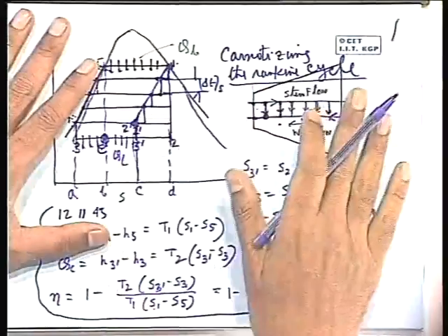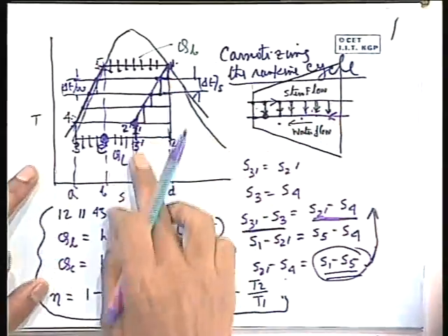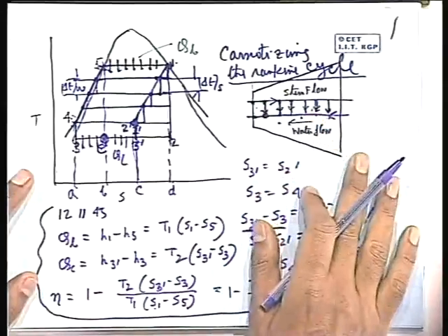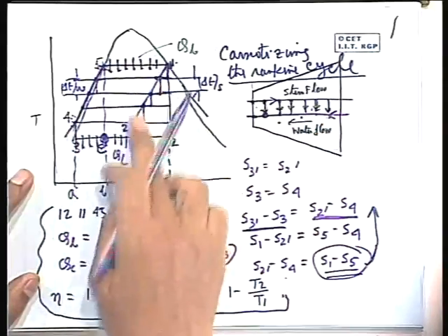Number two is the practical difficulty that we cannot incorporate a heat exchanger tube which runs into the turbine. A turbine is not a device where there is a pipe or some valves through which the steam is flowing and getting expanded and giving mechanical work. This is not the system. To get mechanical work from the expansion of high temperature, high pressure steam, the system is entirely different. So, in that system of turbo machinery, there is no place where I can incorporate that heat exchanger which carries liquid water. So, this cannot be made. So, this entire thing is an ideal thing, and this has been conceived to understand the basic philosophy of the process. That is why it is known as the ideal regenerative system or the ideal regenerative cycle.